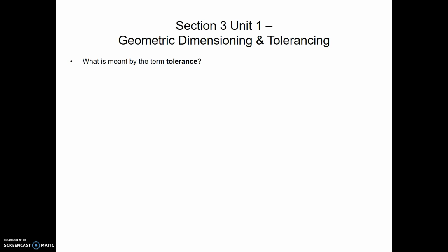If you remember from your CAD classes or other classes, tolerance is an important term because it tells us a little bit about what's good enough, or in essence, the allowable variation in a part size. Depending on what the part must ultimately function as, or what its purpose is, will depend on what limits will be set for variation. Well, one thing we're going to do is use measurement to determine whether part sizes fall within or outside of tolerance. Parts that fall outside of tolerance will not meet the customer's specifications and ultimately will not function to their desired intent.